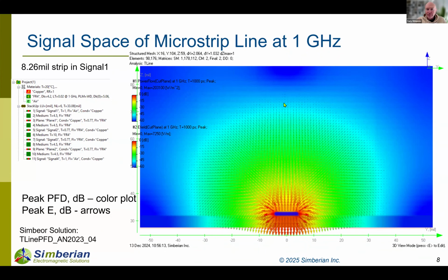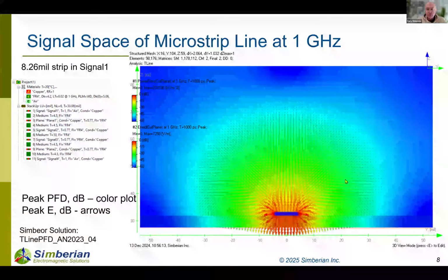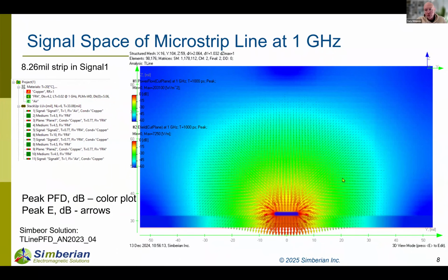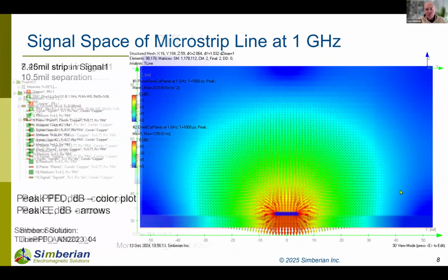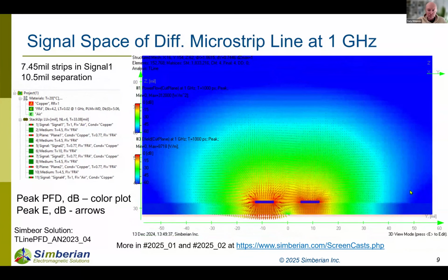So what is the problem? The problem is that we have a large area here, just below minus 60 dB, that is potentially coupled. For digital interconnects, minus 60 may not be a problem, but for RF microwave structures, that may be a problem even beyond this.